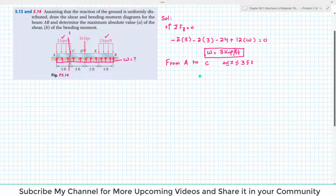When you section the beam, I will draw the free body diagram. So this is the beam, clear. This is the distributed load of 2 kips per feet, clear, and in the upward direction you have the distributed load W, and this distance is taken as x, and x starts from 0 and is less than 3 feet. When you cut the beam at location 1-1, clear, there will definitely be a shear force V and an internal moment M, and let the point where we section the beam be J, clear.